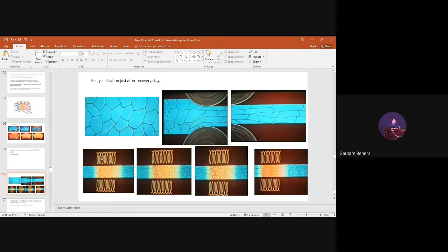So when you heat it, this is a coil. Can anybody figure out what is happening in this material now? Just look carefully in this region. What is happening? Fine grains, sir. Just look at this one and tell me. Yes, recrystallization. Recrystallization is happening. Very good. Small, tiny grains are forming along the grain boundaries and where there are a lot of dislocations.